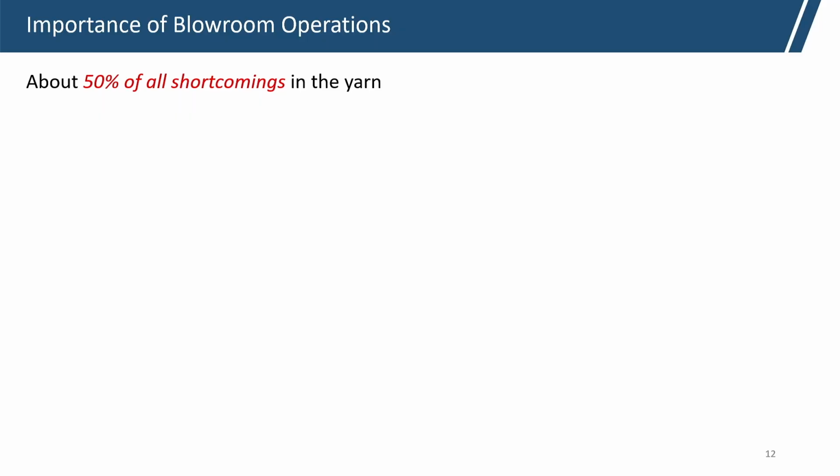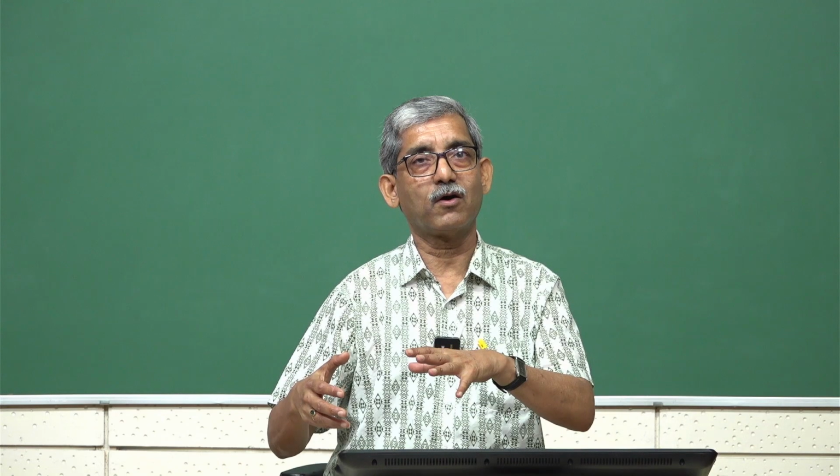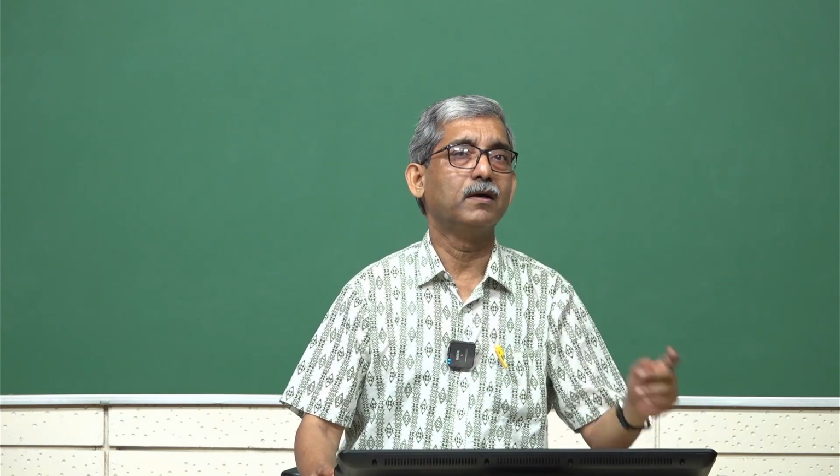Why? Because about 50% of all shortcomings in yarn are generated from blow room. If you see the yarn characteristics, 50% of them can be controlled by proper maintenance, proper setting and proper operation in the blow room.